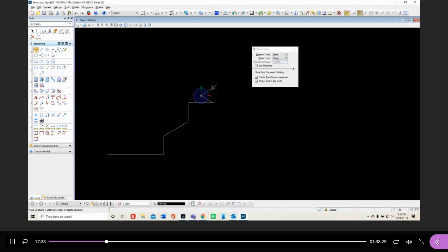And remember, when it does that T shape, that little dash, that means it remembers the distance. So if it's the same distance, I can just give it an angle. And then 1.125. Always go back to your original X and Y.